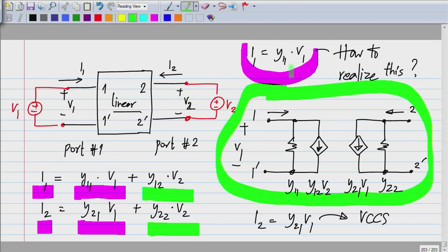But if the Y parameters are the same, they will behave equivalently. You could have one circuit with 100 resistors and another with 50 resistors, and if you arrange it such that the Y parameters are the same, then if you use this black box in some other circuit, they will behave identically.